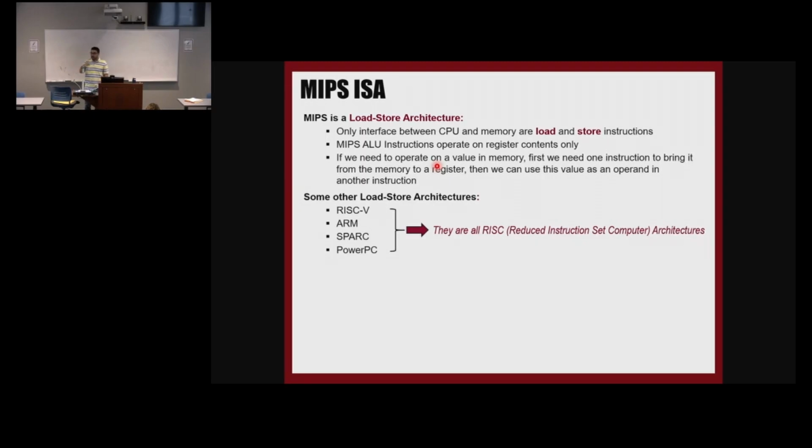So if you have an add instruction, it means that there is an adder in the CPU. If you have a shift instruction, it means there is specific hardware taking care of shift, right? These are basic instructions. So RISC processors, they don't have that many instructions. The instruction set is reduced. It means that the hardware is simpler.